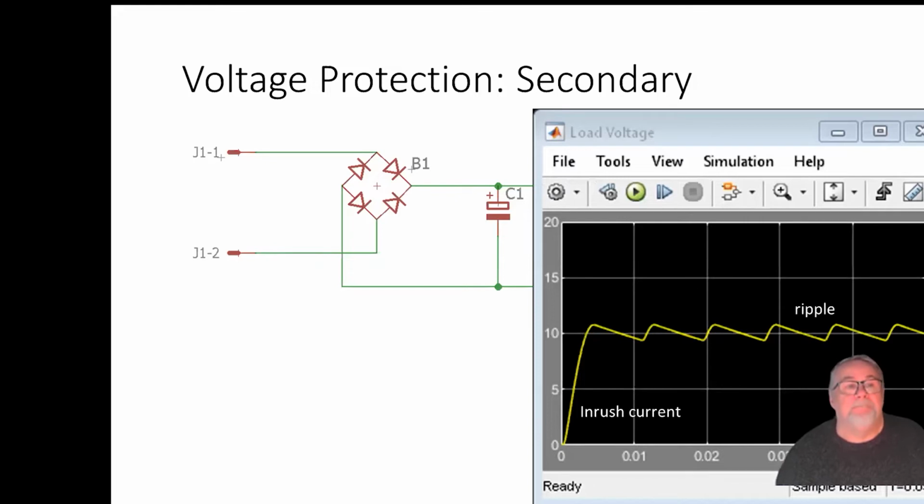And we get that. Two things happen. First of all, ripple. The capacitor charges and discharges and charges and discharges. And as it does so, the voltage in the capacitor goes up and down. When the capacitor's charging, the voltage rises, and then as the voltage tails away, the energy is released out of the capacitor, and we get that long slope in the ripple.